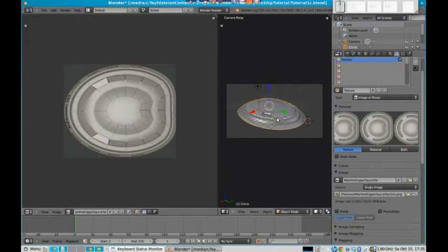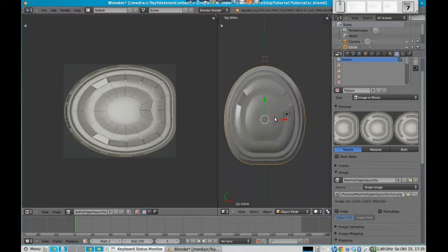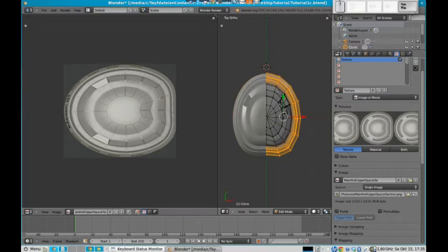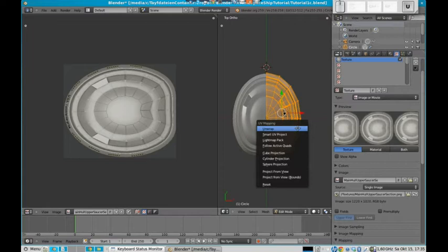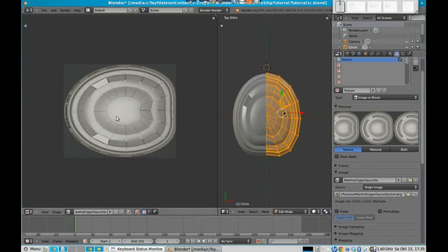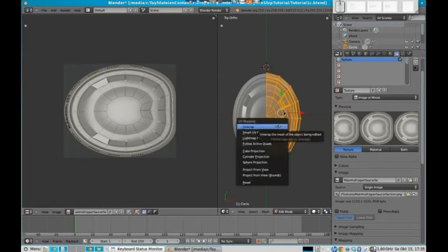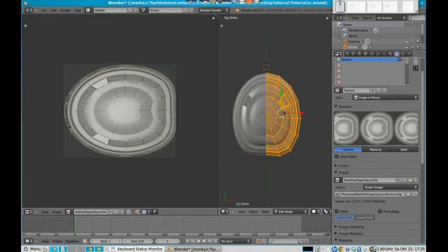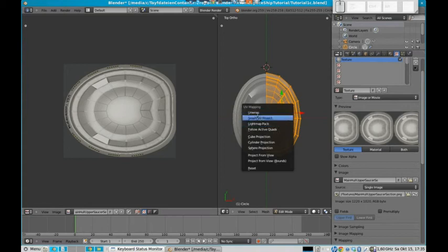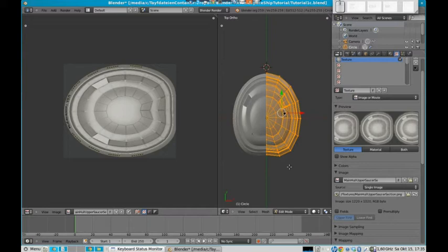So now let's go to the upper view here so that we have it like that. Let's go to edit mode, select all of our vertices and just say U, the key U on the keyboard. That's for unwrapping the vertices here to the UV mapping view. There are several ways of unwrapping that. Some, for example, use smart algorithms, or just a simple unwrapping algorithm, or sphere projection, or whatever.